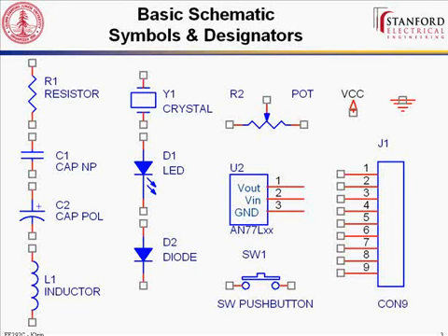So when do we want to separate analog ground from digital ground? All right, so the question is, when should you separate analog and digital grounds? That's a complicated topic. If you're using an analog to digital converter and you're doing something that is high performance, typically you'll need to look at the data sheet for the analog to digital converter, and it will tell you explicitly where the split is between analog and digital. And you'll have separate ground planes that split sometimes underneath the chip or sometimes just off the chip. But those types of designs are tricky. They're more than a 1 semester or 1 quarter class.